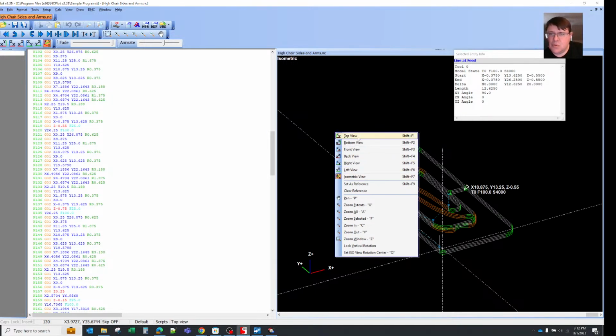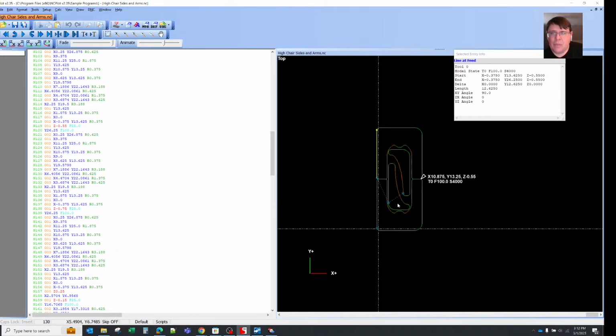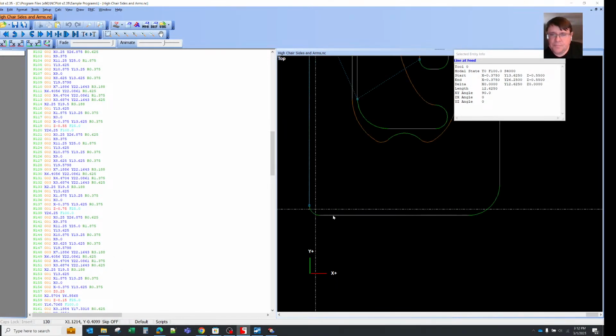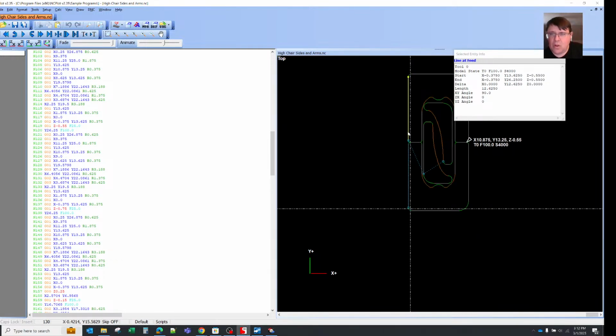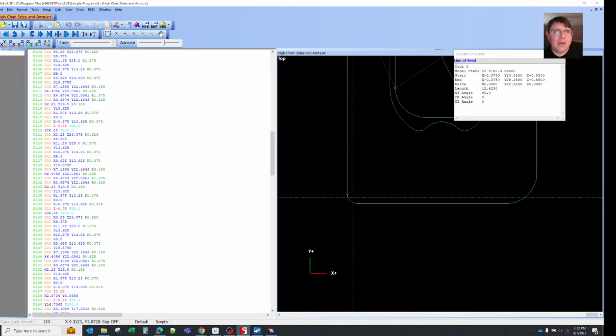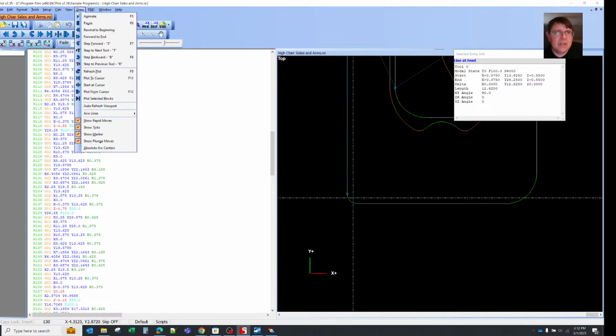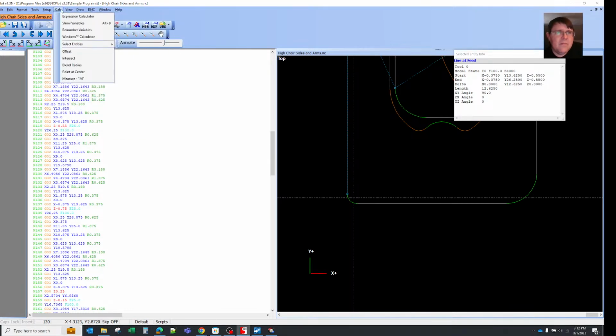So if I go to top view, for example, and I'm now looking visually at this pass, right? These are multiple passes that are coming along some wall or some pocket, right? Some contouring passes, and there's some G code. I actually have the ability to offset.